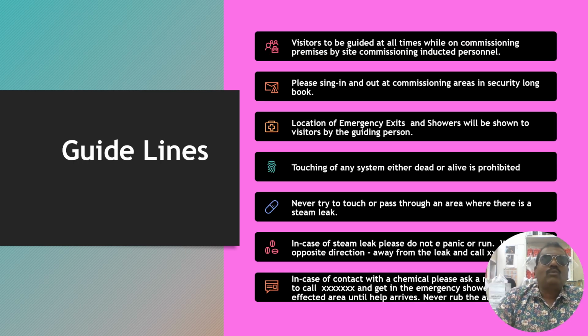So what are the guidelines here? Visitors shall be guided at all times while on commissioning premises by commissioning inducted personnel. Sign in and sign out for the commissioning areas. Location of emergency exit and shower shall be shown to visitors by the guiding person. When a person comes to the site, he should be aware of where the assembly point is, where the power supply is. Everything should be trained for them.